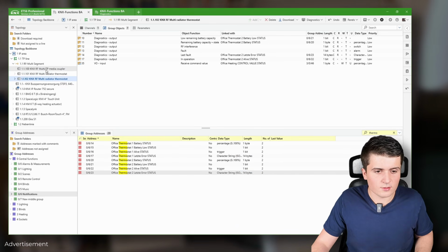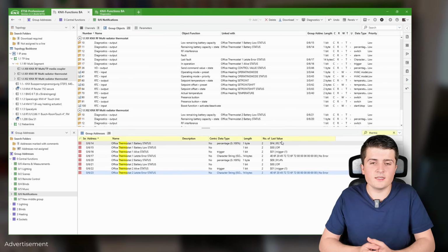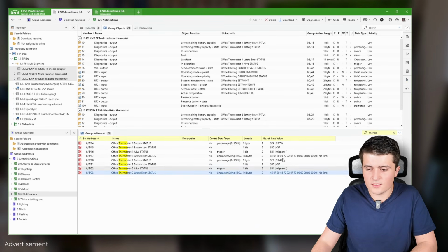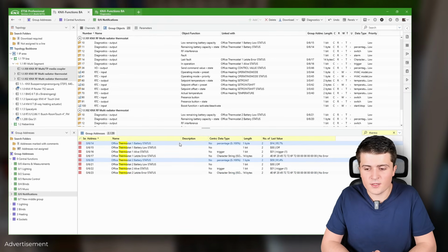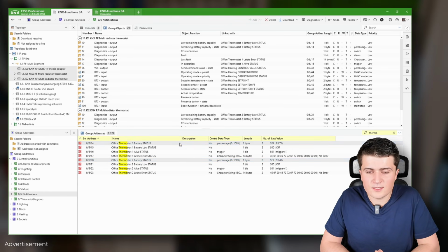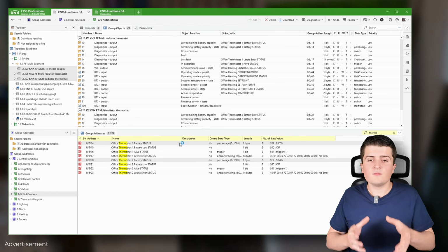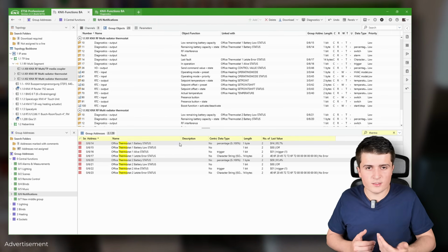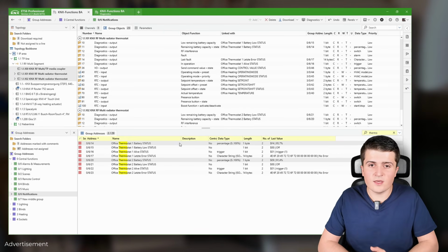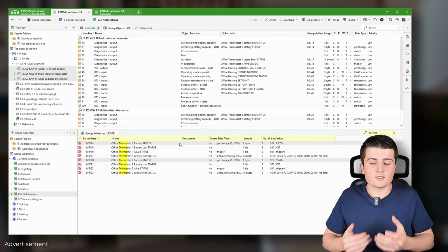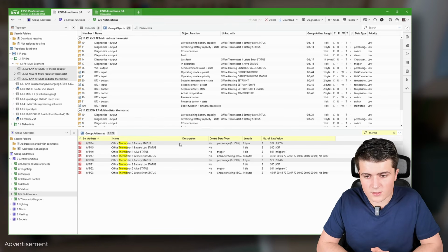So let me quickly download all my RF Multi devices. And you can see the devices are downloaded, and as my diagnosis tools are still running, we get here the information. First of all, no error, which is pretty good. And here we get the current battery capacity. You can see they are still at over 90%, and those thermostats are now nearly running 1 year. Now, to be fair, my demo installation is not running 24 hours a day. However, the thermostats are installed 24 hours a day, and you can see they are still at over 90% battery charge. So I can definitely say that the battery lifetime is pretty good with those KNX RF Multi devices.